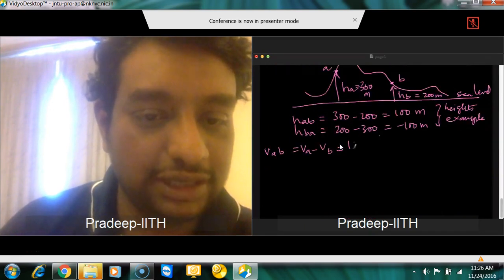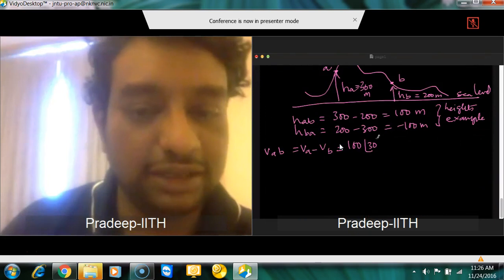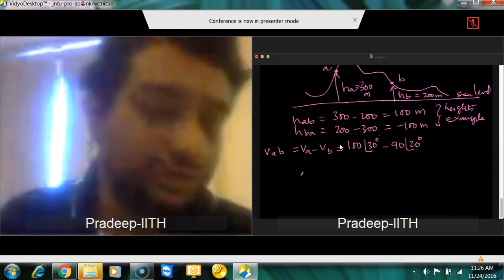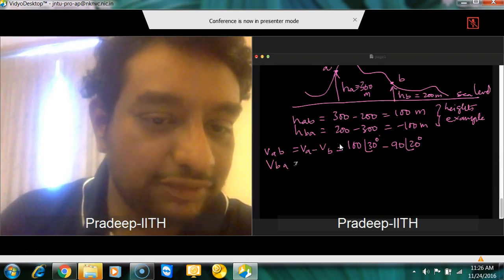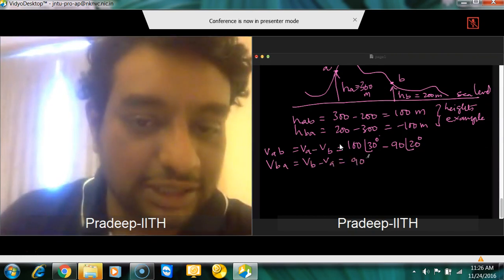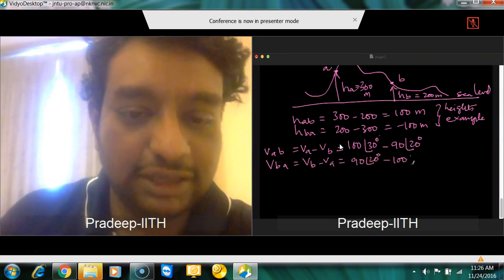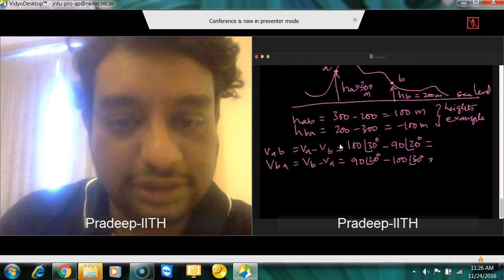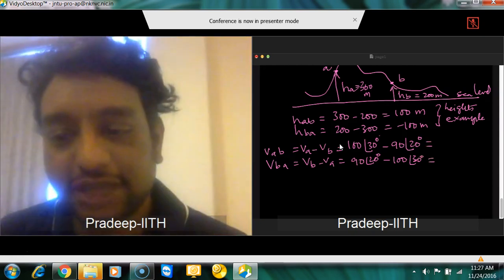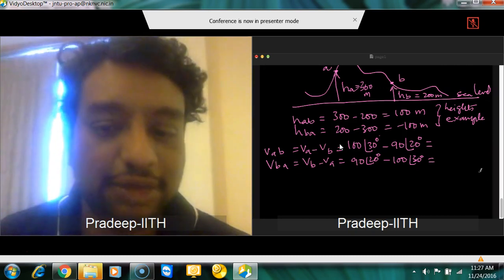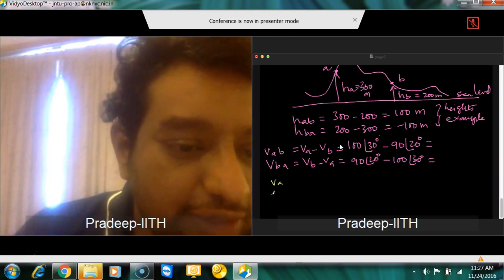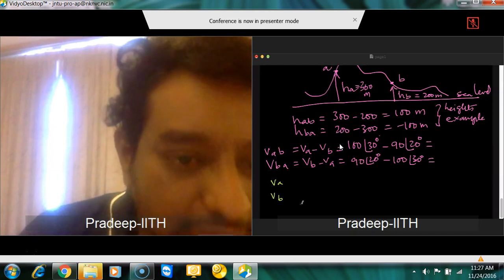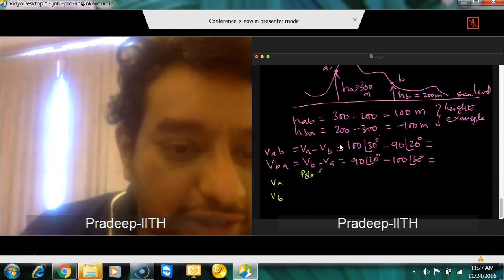100 angle 30 degrees minus 90 angle 20 degrees. What is VBA? It is nothing but VB minus VA, that is 90 angle 20 degrees minus 100 angle 30 degrees. In order to do this calculation, again you need to go back to the polar and rectangular notation. VA and VB are in polar notation: 100 angle 30 degrees and 90 angle 20 degrees.